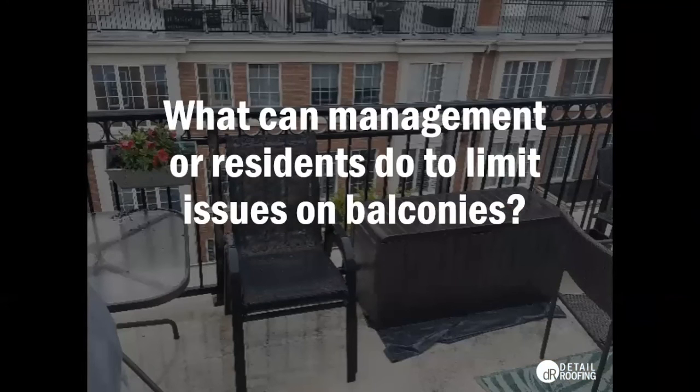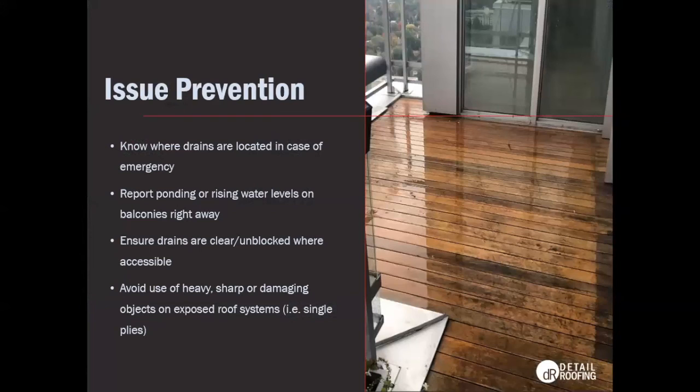So overall, what can management or residents do to limit any issues on balcony and terrace roof surfaces? So again, due to the amount of issues that stem from drains, number one is knowing where the drains are located can be very, very helpful in case of emergency. If there's really heavy rains or any flash flooding occurring, knowing where the drains are in case you need to quickly check them and unblock them to prevent any flooding issues can be very, very helpful.